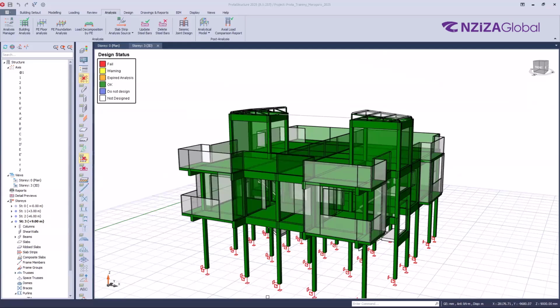Okay, so what we design are the reinforced concrete members. The wall load was the masonry wall, so just masonry walls. So we are not designing those masonry members. Only what needs to be designed is the slab itself, where the load is being applied to. So we are not designing masonry members, just reinforced concrete members.